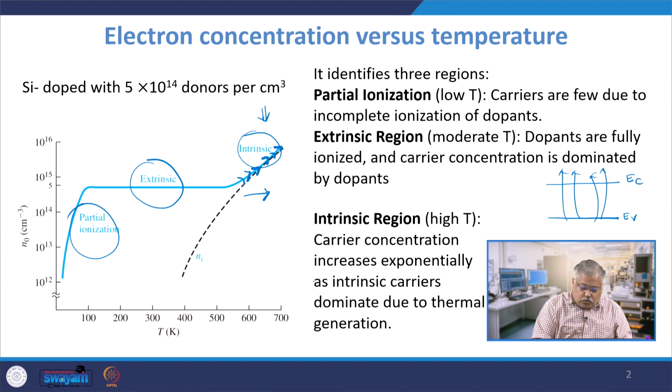As you now go towards a lower temperature, a time comes, typically around 100 to 500 Kelvin, where the number of charge carriers is fixed because all the dopant species have fully given their charge. Let us suppose you have doped with 100 atoms of a group 5 element, which is phosphorus.